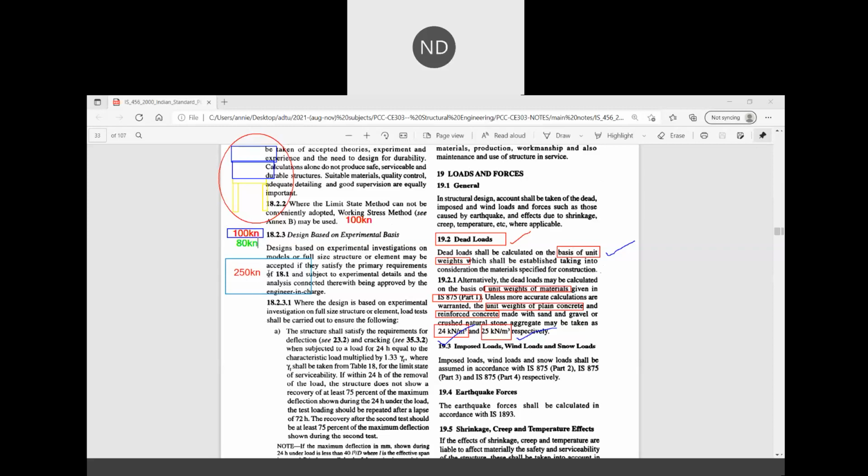But it is not necessary for us to put this beam here, because according to our estimation, this is going to cost us more, since more material will be required in this larger beam as compared to this beam. So we'll use this beam, because we needed 80 kilonewton to resist, but it can resist 100 kilonewton, so fine for us, no problem.